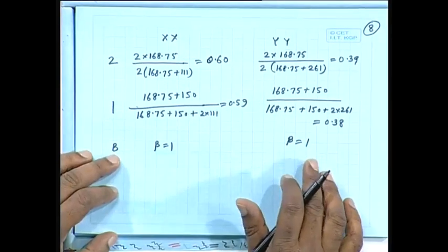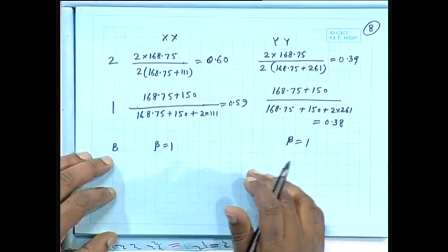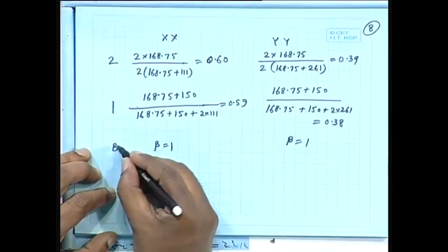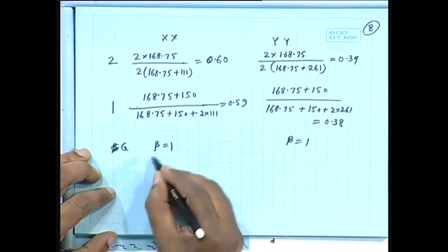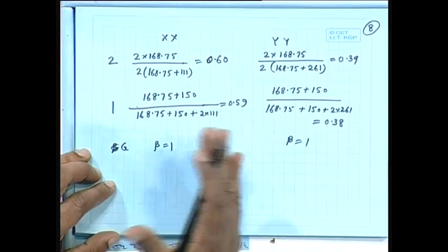Yes, for the bottom we have taken the basement, or let us call it ground. We can take that particular point because we are not transferring any load to the foundation for bending, only axial load. That means in another way you can consider it as a hinged condition, and that is why you are taking beta equal to 1. If you want to design for bending, then you have to calculate that beta accordingly, taking the foundation depth, say 1.2 or 1 meter, whatever you have provided. But in most cases we take beta equal to 1.